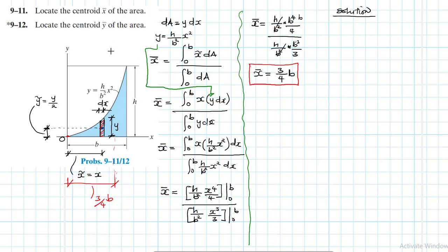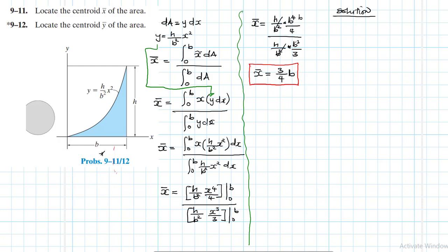All right, so this is about it. So let's move on to the next stage. I'll need to wrap this, so that I draw another strip, but this time around in the y direction. Okay, all right, is that fine? Great. So there we go. Let's draw another strip. This time around we are locating a centroid y bar of the area. Okay, so let's draw another strip like so in this direction.